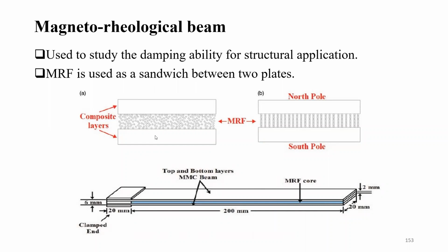If you have a composite layer, or steel layer, or aluminum, actually the way Saab has done with the aluminum layer, if I'm not wrong, aluminum plate, 1 mm or 1.2 mm, and then you use the MR fluid, then you change the current. Either they must have used a permanent magnet. In fact, we can also develop some system for electromagnet. Then you apply, and the vibration of this composite plate can be controlled by controlling the current at various points.